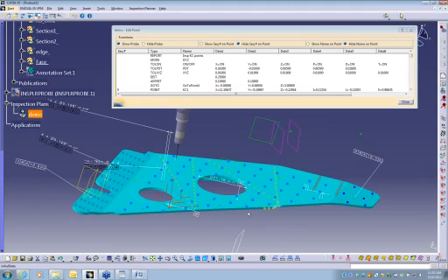Where it can be used, where I use it on, we have a Faro arm, Romer, and I use VeriSurf, and we also sell VeriSurf software. Where I use this solution is if I want to set specific measuring points. If I create these points in CATIA, and I save the CATPart, and I go into VeriSurf for example, with the CATIA read, if I read this model into VeriSurf, these points come in,